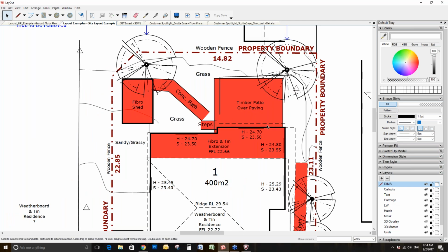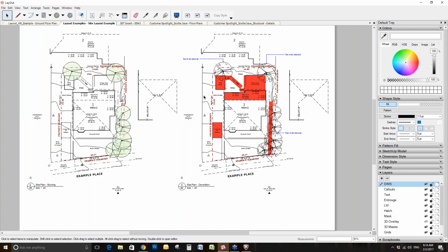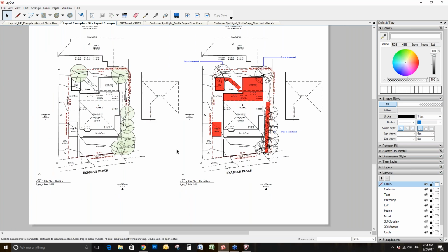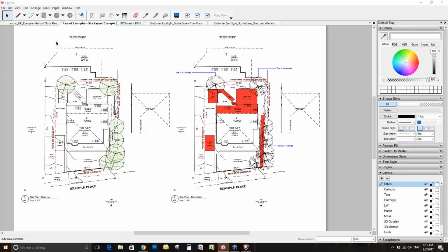Secondly, you can also lock layers so you're not accidentally moving them. So once you've brought in, for example, your PlusSpec for SketchUp model and you've set it in place, but you don't want it to be accidentally moved or modified, then you can simply click on the lock layer. So these are directly input from my PlusSpec for SketchUp model, and I've got several in this particular file. Before I go any further, I'll quickly jump into another example. These ones are examples in metric, but I will give you a customer spotlight, and that will be in imperial.